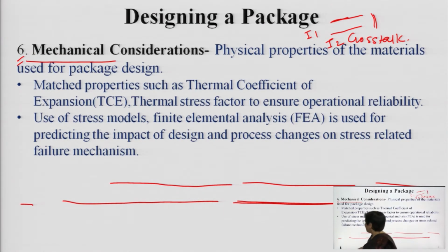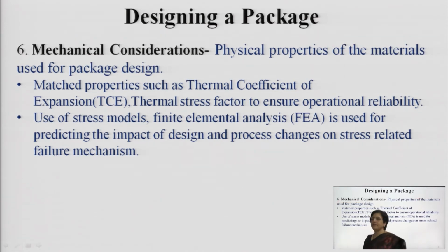Lastly, we need to take into account the mechanical considerations, and these mechanical considerations are basically related to the physical properties of the materials which are used for the packages. Now these package materials have to have properly matched thermal coefficients, that is, we call it TCE, thermal coefficient of expansion. Now this thermal coefficient of expansion relates to the stress factor, and any stress associated with elevated temperature is to be properly handled by the package material which is being used.